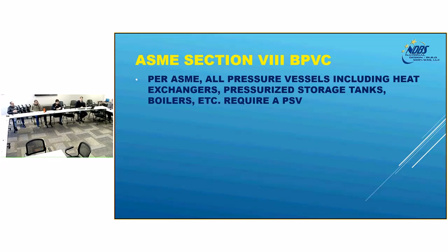So one thing to consider, you think of vessel, you think of a big contained vessel. It's not just the large tanks. It's any heat exchanger, any part of the system that is defined as a boiler or a reboiler, or is larger than, I think it's 4 cubic feet in volume, then it's considered a pressure vessel by code.